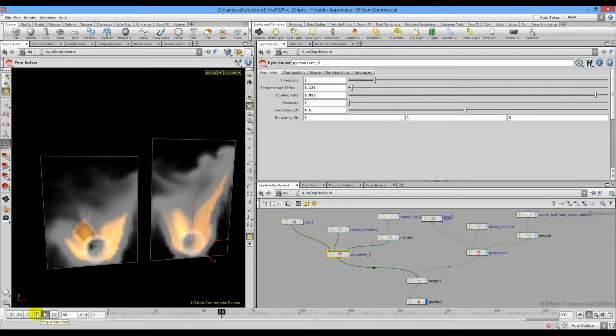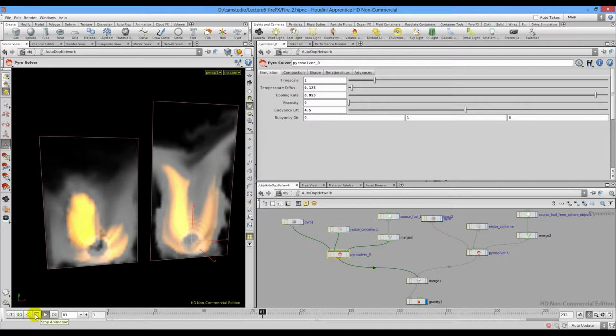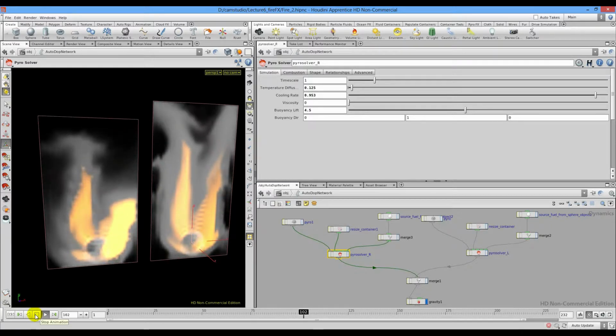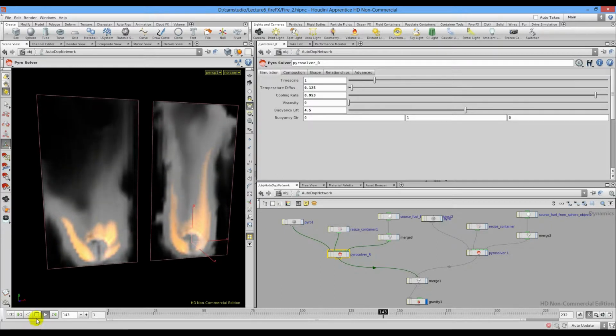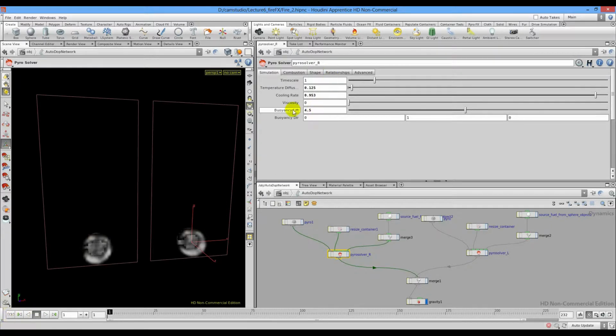The flame is kind of weak and very little, and smoke is really subtle here. All right, and it was 0.8. As you remember, the bold values aren't default, but here it's default for this preset. So just bring it back to keep it the same as this solver.